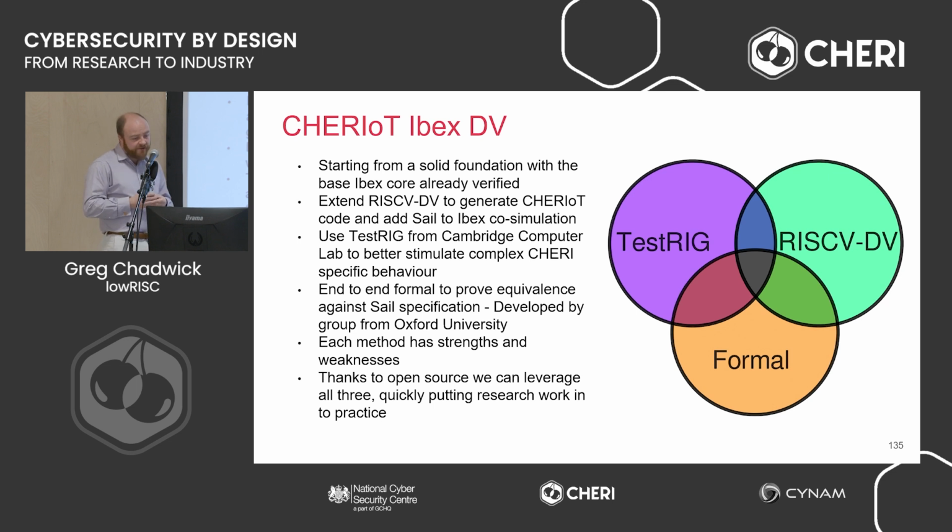There's also a new methodology that we're looking to use called TestRig, which again comes out of Cambridge Computer Lab. They designed TestRig to help them test some of their CHERI processors, and again, we'll be looking to use this to help verify CHERI IBEX. TestRig is really great at getting into some really detailed corner cases that you might find in a capability-based architecture. So it's really useful for testing complex CHERI-specific behavior, which is why Cambridge Computer Lab built it.